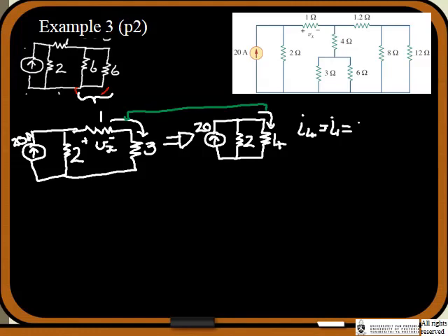It is going to be the total current I, which is the 20 amps, multiplied by, now the trick is what resistance. At the bottom it's going to be the 2 ohms plus the 4 ohms. It's always the sum, but now what resistor comes at the top? We want the current flowing through the 4 ohm resistor, so at the top needs to be the other resistor, R2.